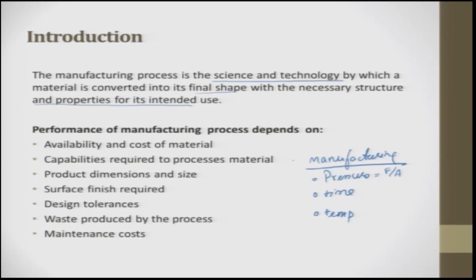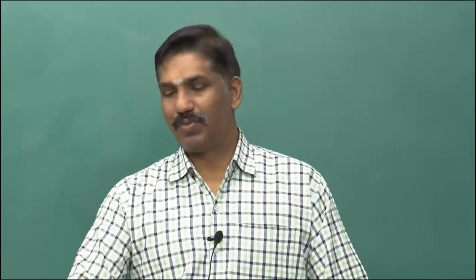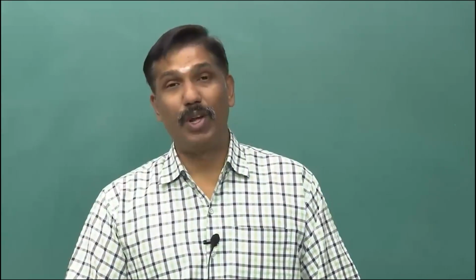The only thing is the weightages of individual parameters are still not known, or during the process the weightages keep dynamically changing, which is very difficult for us to understand and model. That is why many a times the manufacturing process is said to be trial and find out, or hit and go. That means you do some experiments, you get a good output, then freeze the parameters, saying these are the best parameters for making this output. It need not be optimum.